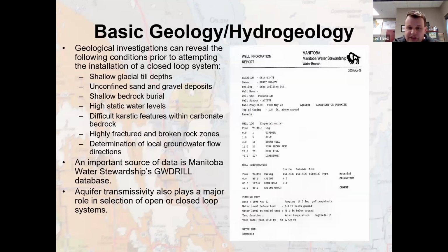Some of the issues that we tend to see more commonly are that the basic geology and the hydrogeology are somewhat missed. Geothermal technologies tend to involve either shallow or deep closed loops. What's interesting is that we often see these approaches used when a deep closed loop system is going to run into very shallow bedrock conditions, and people didn't anticipate that.